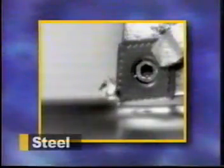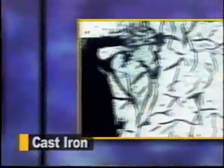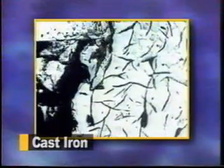When cutting steel, the resulting continuous chip causes both top and edge wear on the insert. Discontinuous chipping materials, such as cast irons, are more apt to cause edge wear because the chip breaks before flowing across the top of the insert.